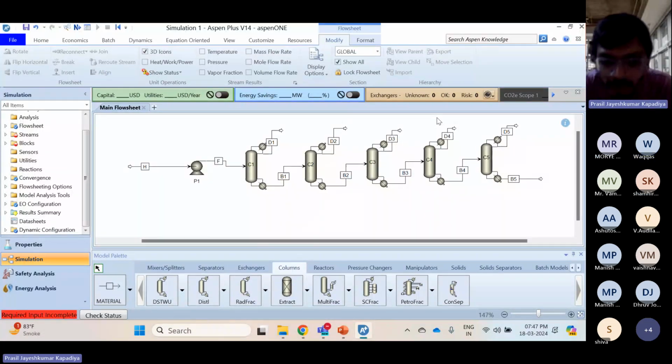Okay, I'm just stopping you. Yes, Vaishnav, say. Also, we can use a multi-fraction distillation column for this. Okay, multi-fraction column. Vaishnav, you are saying something. Same thing, sir, multi-fraction column. Yes, we can't do it with one normal distillation column because of this thumb rule: if we want to separate n components, we should have n minus one distillation columns. Ideally, we should have n minus one distillation columns to separate each of the components.